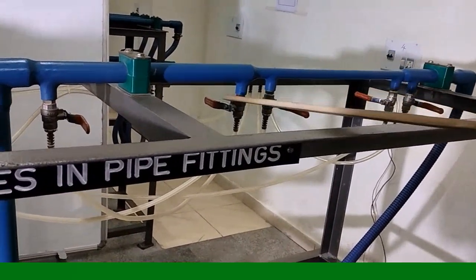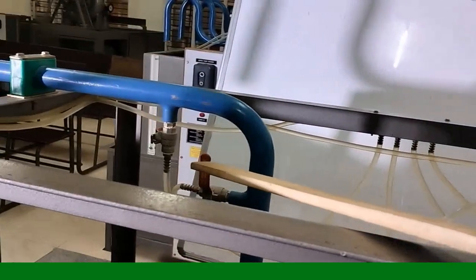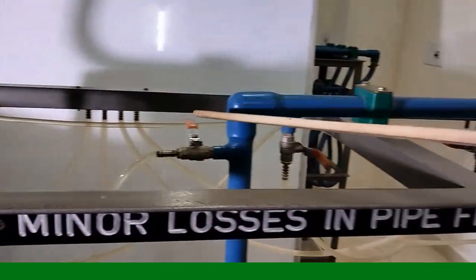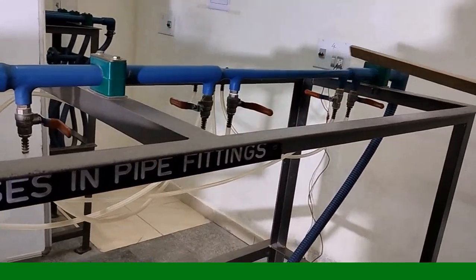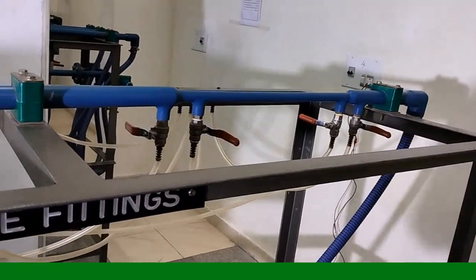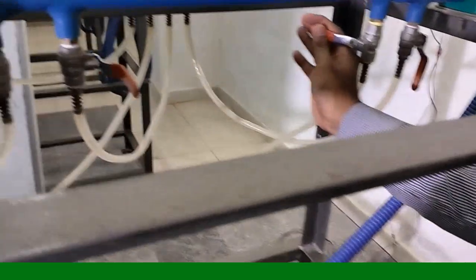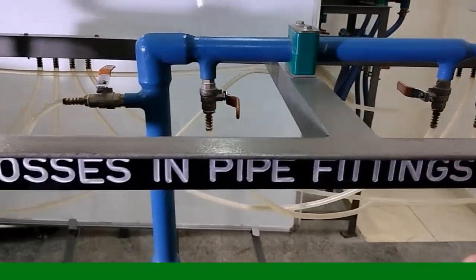Once you make sure of that, open only the pressure tappings for the experiment you are going to carry out; all remaining pressure tappings must be closed. Now switch on the motor, and using this valve conduct the experiments for different flow rates.